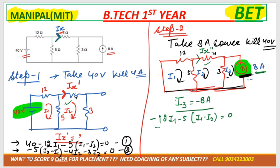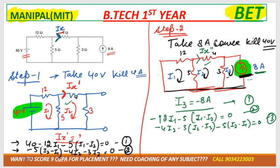Okay. For the first mesh, the equation would be minus 12i1 minus 5i1 minus i2 is equal to 0. For the second mesh, minus 4i2 minus 3i2 minus i3 minus 5i2 minus i1 is equal to 0. So from here we'll get three equations, three variables. Can we solve and get the values for i1, i2, i3?